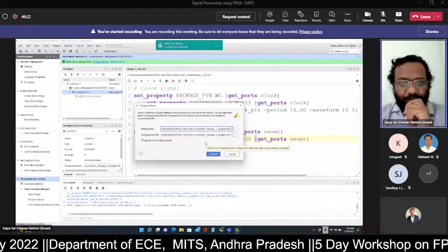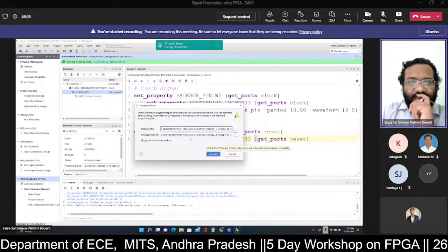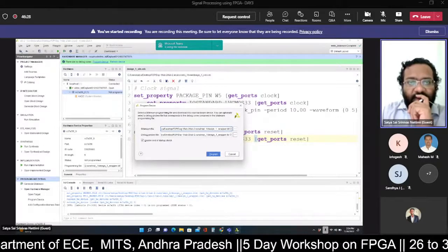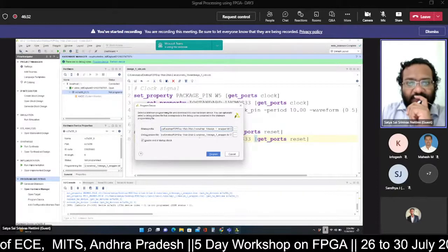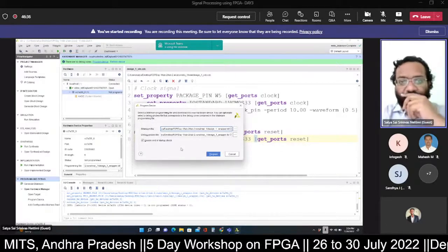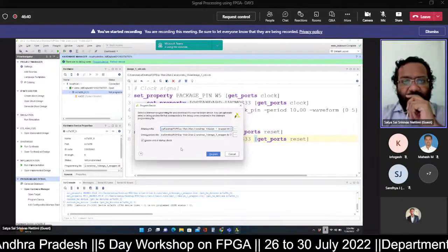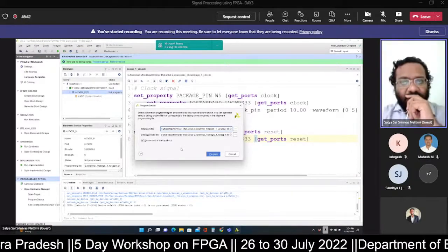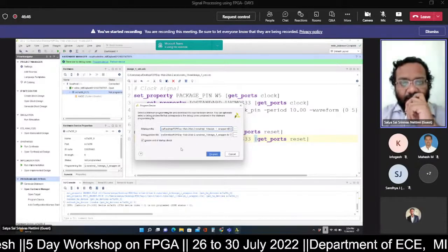Earlier, when we programmed our FPGA, we noticed only the bitstream file, and there is also a section called debug probes file that was empty earlier. Why? Because we had not used any debug probes. But in today's design, we have integrated a VIO IP core and an ILA IP core. These two cores are referred to as debug IP cores.